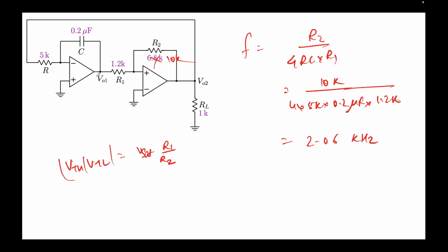Remember, VO1 was limited by plus minus VTH, right? So when we are increasing this, we are reducing that limit of swinging. This means that VO1 will achieve the requisite voltage faster, right?